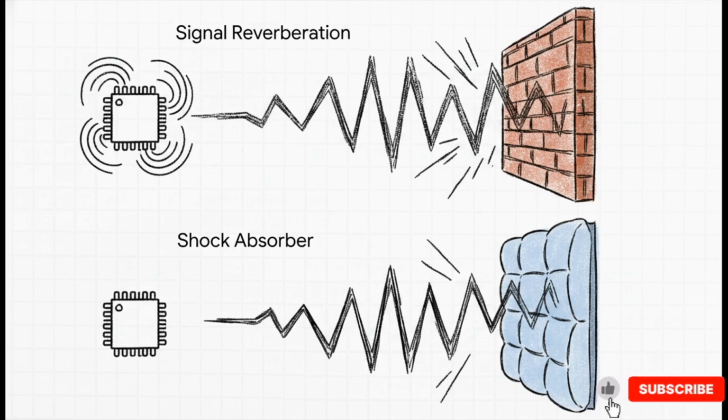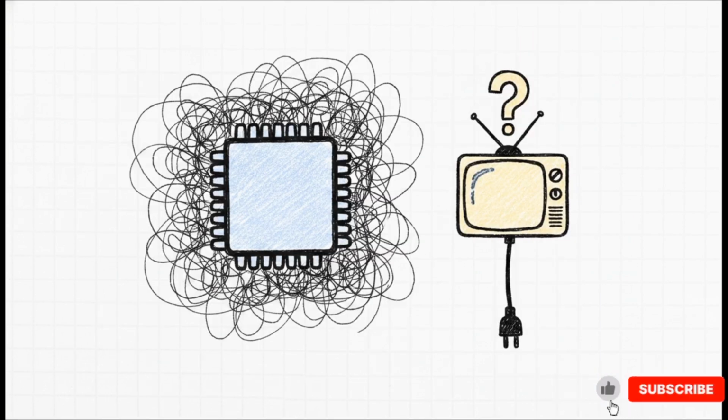When the TV's processor fetches data, that data travels down a transmission line. If it hits the physical end of that line without being properly absorbed, the signal echoes and reflects backwards, literally deafening the processor with overlapping electronic noise. The DDR terminator chip provides that essential end-of-chain absorption voltage, usually sitting right around 1.25 volts, just to catch and neutralize those data echoes.